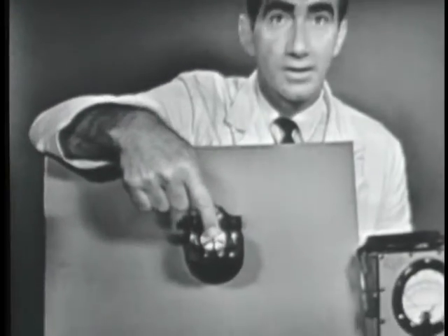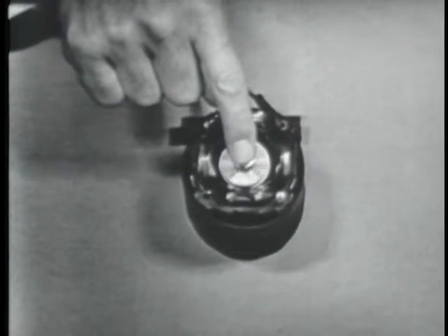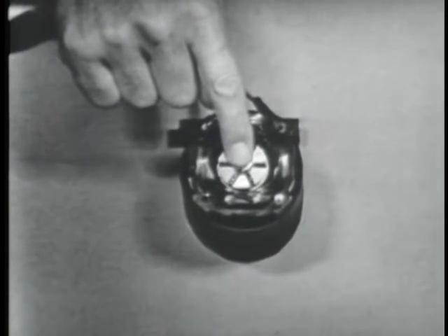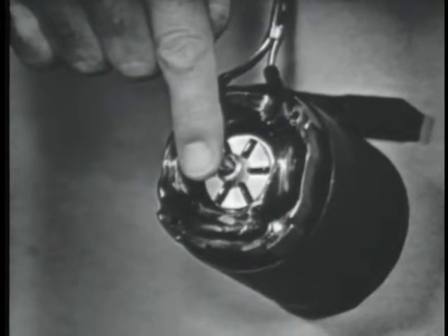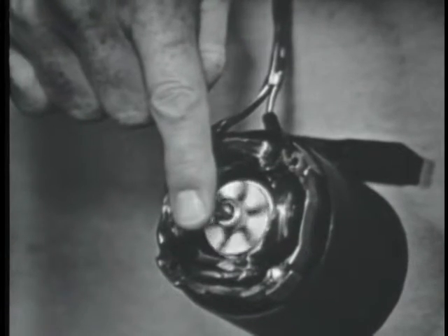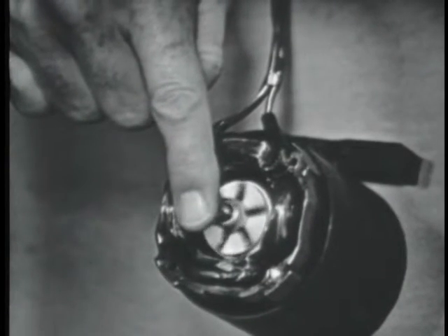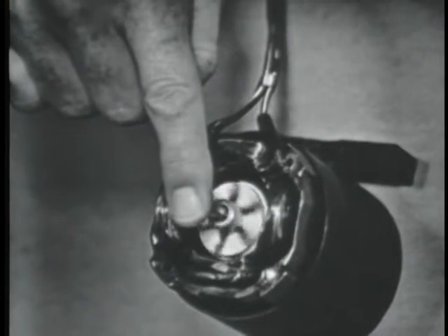The load of the fan causes the rotor to slow down, just as I can do with my finger here. I can cause the rotor to turn slower. Now, as it slows down, the slippage increases, and the frequency at which the conductors of the rotor are cut by the rotating flux lines increases. More current flows. The magnet becomes stronger and compensates for the increased load.